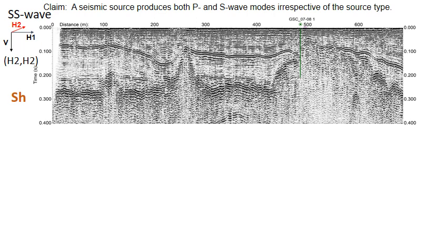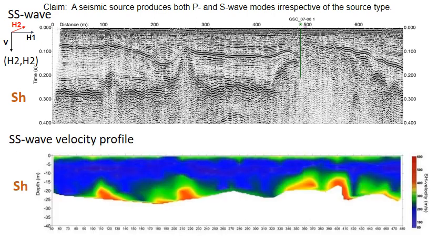The velocity analysis allows us to plot a depth section highlighting various interval velocity units. These types of velocity plots are what civil engineers usually need for the planning of construction, tunnel digging, or to test levees and earth dam construction. This then allows a geologist to interpret this section.